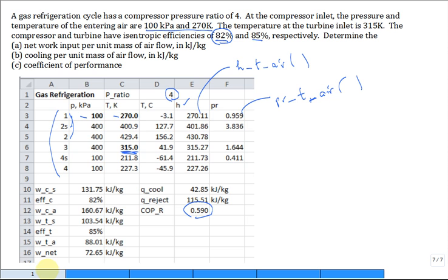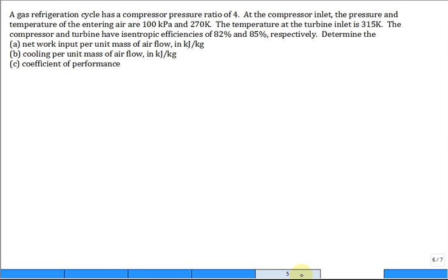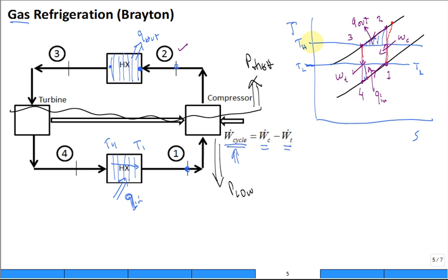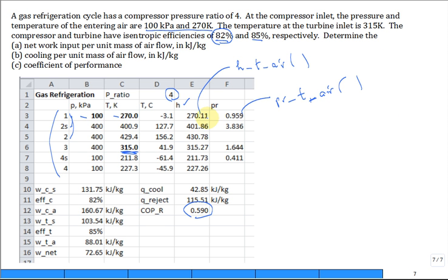Because of the turbine? It's really because the T low and the T high are so close together. So that's it. The turbine, you use entropy, right? And if it's like a valve, yeah, so it's all enthalpy changes. So the work that the compressor consumes, if it's isentropic, is this difference. And then you divide by 0.82, and so you find it takes more work. And so you add that to 270 and just walk around the problem. It's a Brayton cycle run backwards.